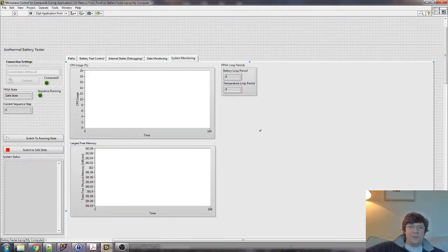And we can have a look at what the system's up to. So this is our CPU resource usage, and our total. At largest, what's it total? In this case, this is meant to run on a sbRIO 9637, so it doesn't give you access easily to the largest physical memory block that's free, whereas on the 9636, which was a VxWorks platform, you did get the largest free memory block easily available, so I changed it to total free memory, but it's a minor thing.